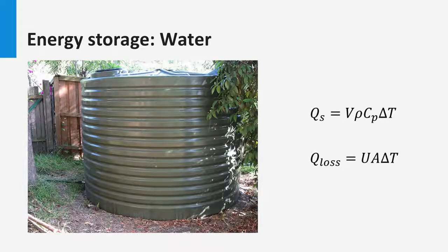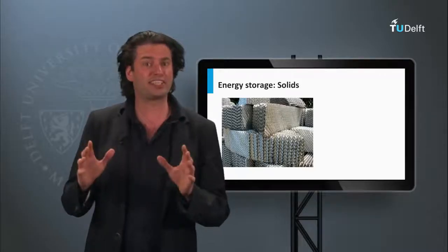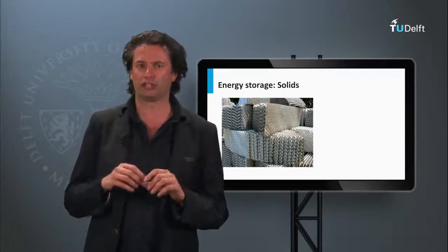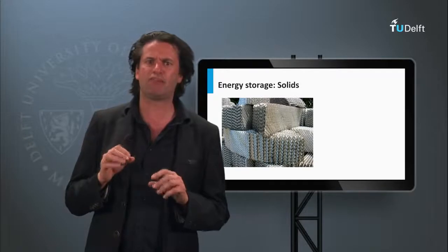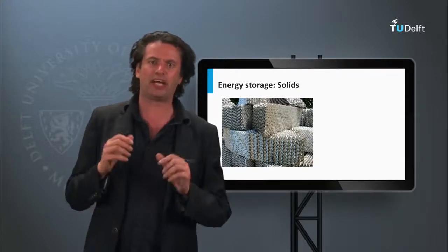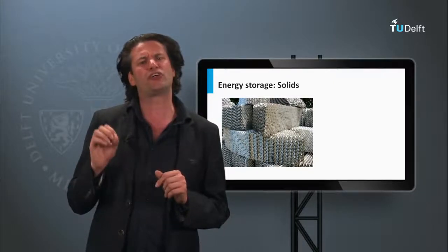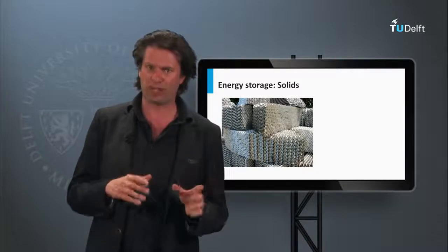The same principles can be applied to smaller or bigger systems. Small water energy storage can cover daily fluctuations and is usually in the form of tanks. On the other hand, bigger systems can be used as seasonal storage, typically in underground reservoirs. Another type of energy storage is the so-called packed bed. It's based on heat storage in solids. It uses the heat capacity of a bed of loosely packed particulate material to store energy. A fluid, usually air, is circulated through the bed to add or remove energy.